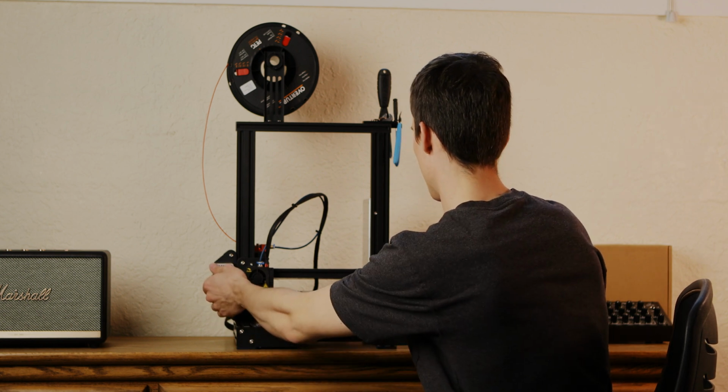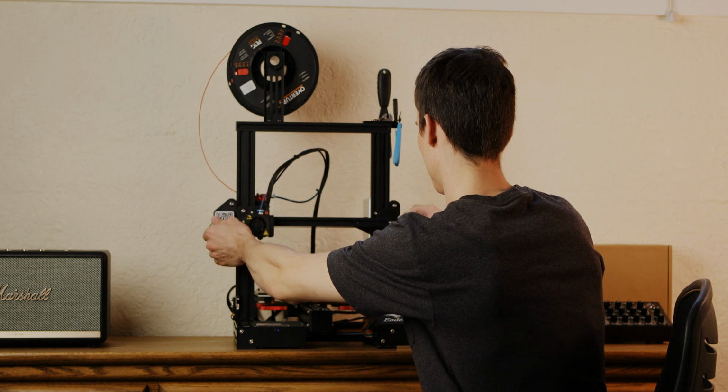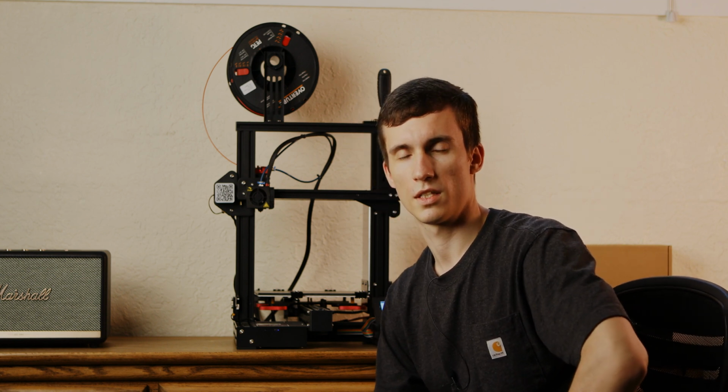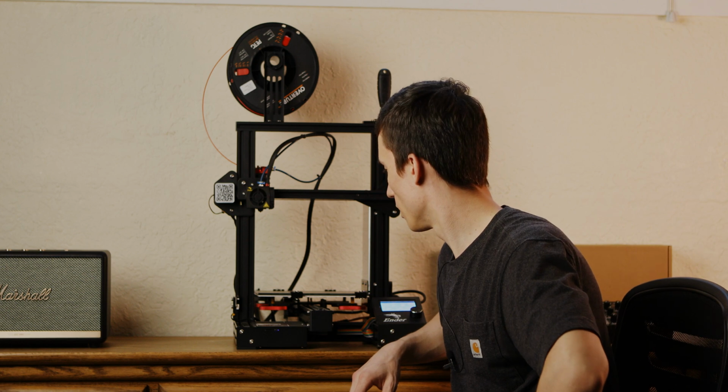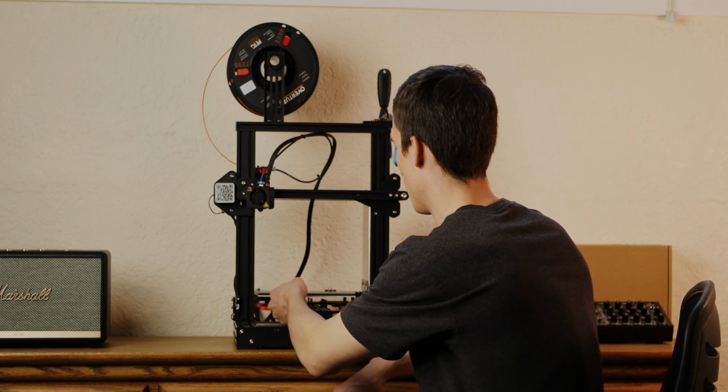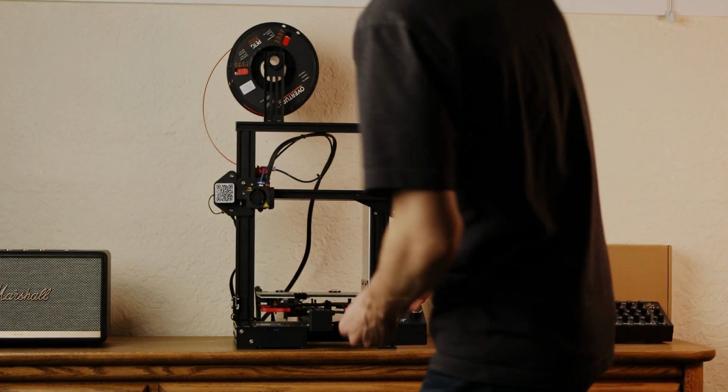and lift up the z-axis. And while doing this cleaning, for the stock bed I mainly use 70% isopropyl alcohol, I believe, or something like that. And that really gets out all of the previous plastic residue. For this bed, the manufacturer states that you need to have just plain water as the cleaning. Whatever cleaning solution you use, it has to be just water. I don't know about soap, I didn't read up on that, but that's what I use. I just get a microfiber cloth and wet it and wipe the bed.